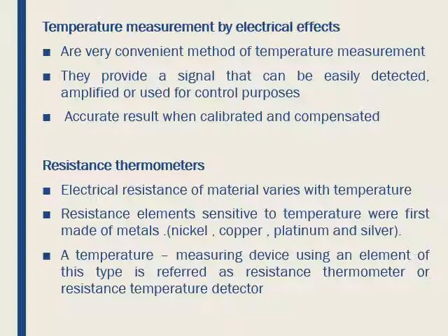The laboratory work thermometers have a scale engraved directly on the glass stem, while the industry type have a separate scale located adjacent to the stem. Quite often, the top of the capillary tube is also bulb shaped to provide a safety feature in case the temperature range of the instrument is inadvertently exceeded.